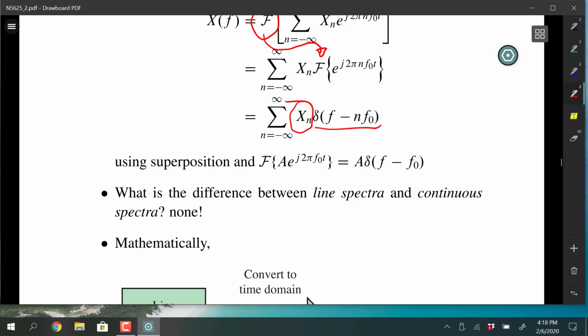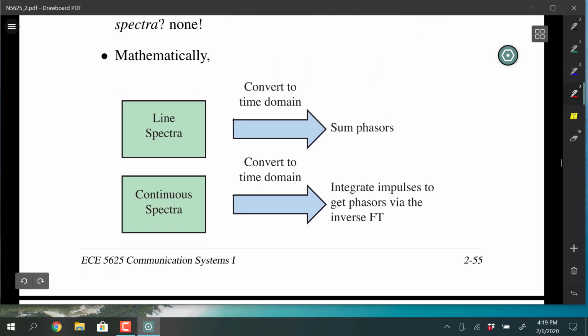When you take a Fourier series representation, you have that x of n, and you have to say, okay, x1 is going to sit somewhere, and I have to go and say, well, what's the fundamental frequency, and what harmonic am I talking about to actually locate it on the line spectra axes. Whereas mathematically, if we do it this way, the delta function automatically places the spectral line on the frequency axis. What do you think? That's what I'm telling you. Does that seem nice? There's really no difference. It's just that I like the delta function better because it locates the spectral lines in math.